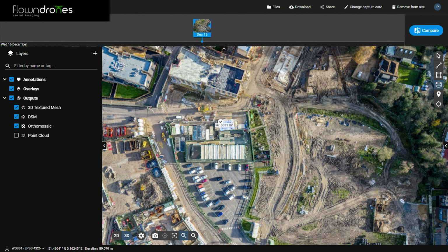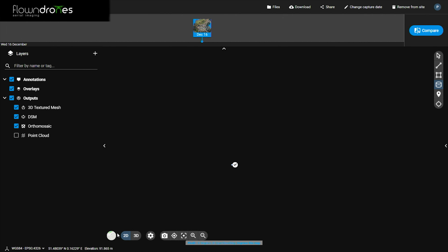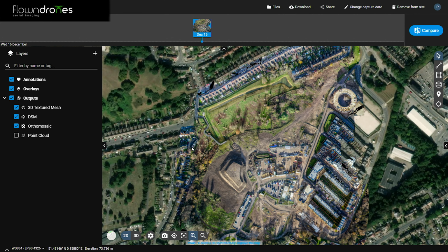And then the accuracy of these, there's a link in the description below to some of the research that's been done on them, but this particular map is done with a drone using GPS, so you're probably looking at accuracy of less than a metre. You can see on here as we zoom out and overlay it over existing maps, things line up pretty well, but the accuracy does depend somewhat on the GPS signal strength. We are able to offer 1 to 4 centimetre accuracy using more expensive and advanced RTK drones that cost extra. But again, it depends how accurate you want things to be.